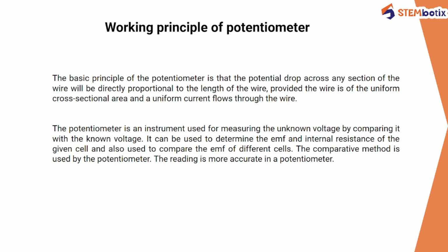The potentiometer is an instrument used for measuring the unknown voltage by comparing it with the known voltage. So potentiometers are also used for measuring the unknown voltage. It can be used to determine the EMF and internal resistance of the given cell, and also used to compare the EMF of different cells. The comparative method is used by potentiometer. The reading is more accurate in a potentiometer. So the potentiometer's readings are more accurate.